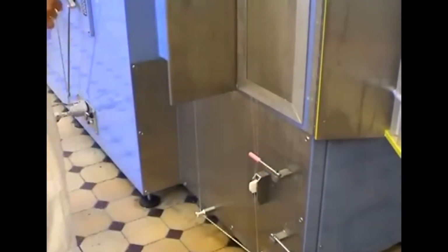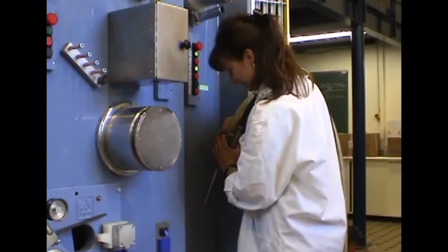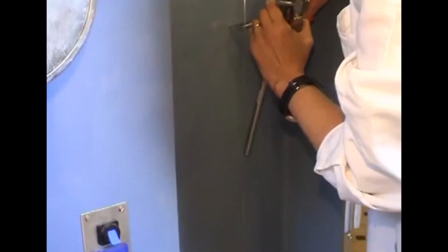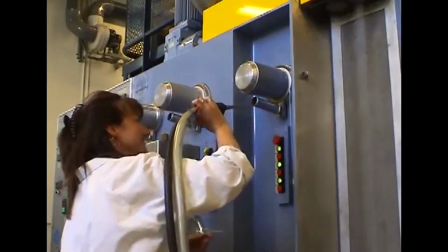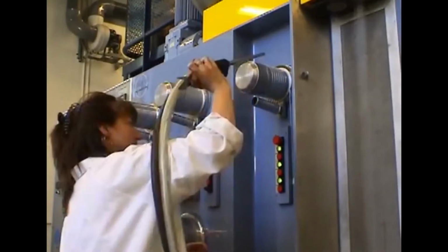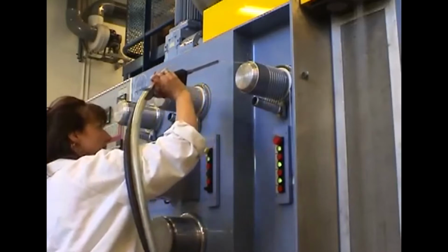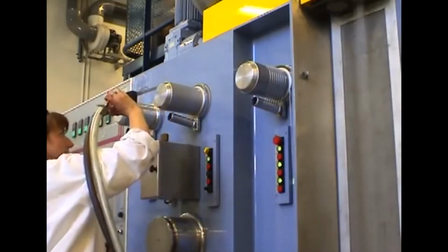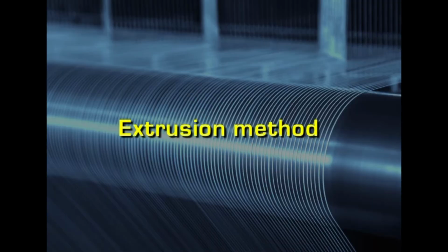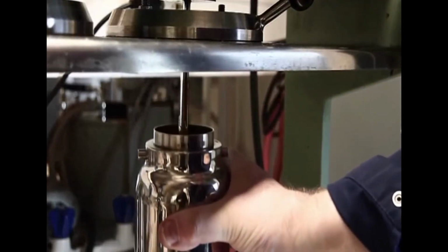Depending upon the type of polymer that is used and also the type of material that is present, whether it is a volatile solvent or a non-volatile solvent, the methods differ. And so, sometimes this chemical spinning is also called the extrusion method. That is, we have to make it into solution and then it should be extruded through the spinneret. So, this is also called extrusion technology.